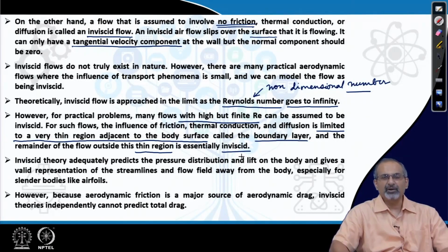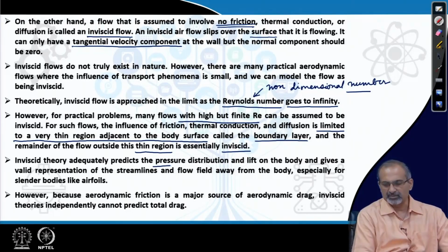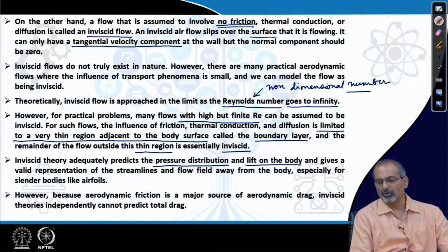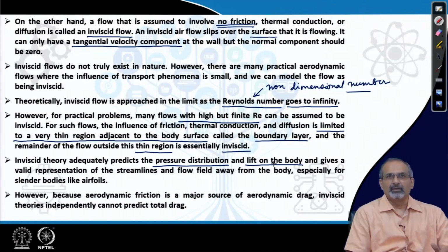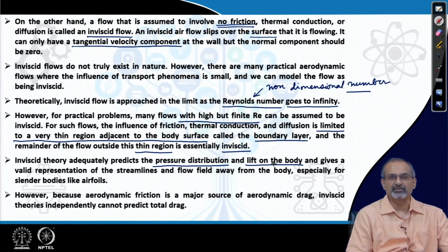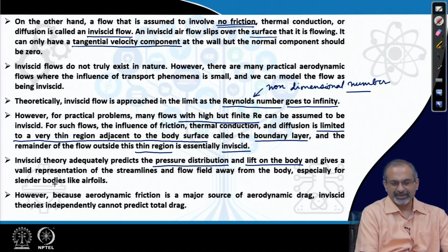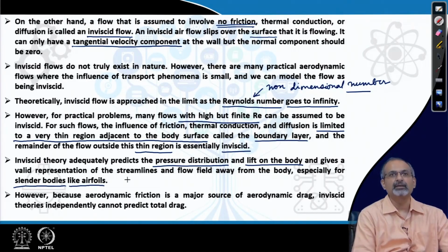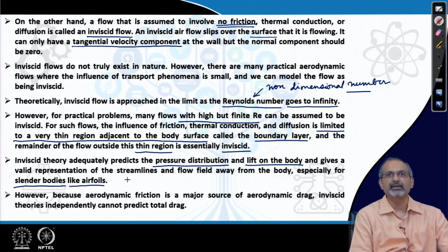Inviscid theory is very powerful in predicting pressure distribution and therefore lift on the body, when the angle of attack is not substantially large. The results are very encouraging, and it can also predict the flow field patterns through the streamlines. It is especially true for streamlined bodies or slender bodies like airfoils, especially at low and moderate angles of attack.